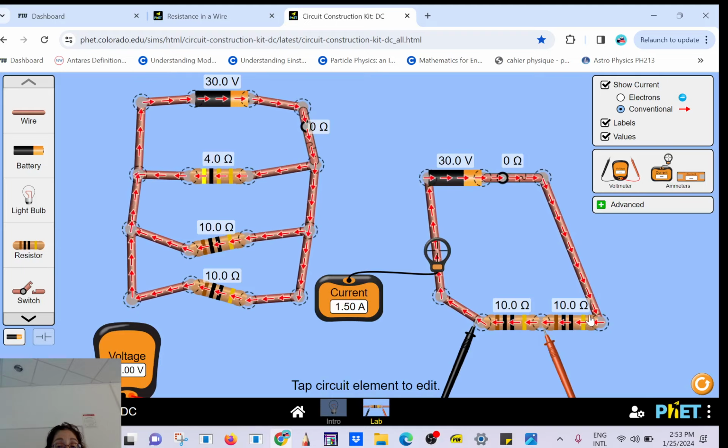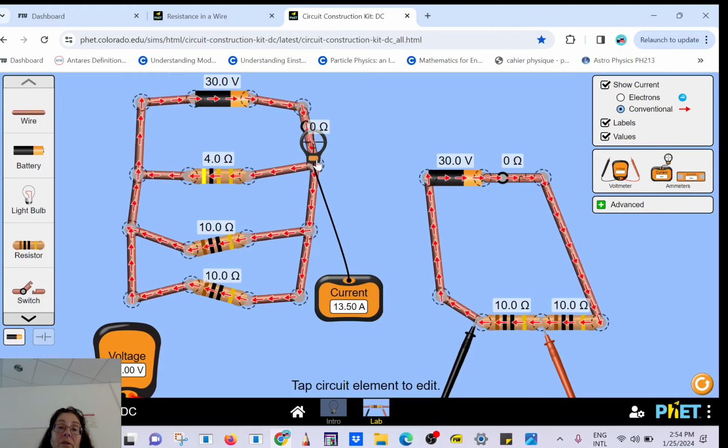As you increase the number of loads, you decrease the current, and you decrease the voltage across each of them. So they don't get the energy they would like to get. In parallel, each one is doing its own business. They are ignoring each other and they get the current they want and the voltage they want. Except that the price to pay, of course, is that you are draining a lot of current from the power supply. Is that clear?